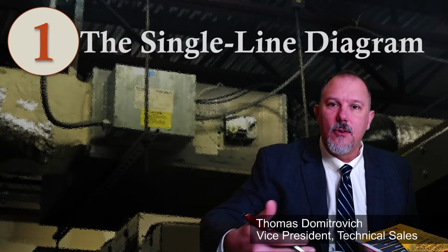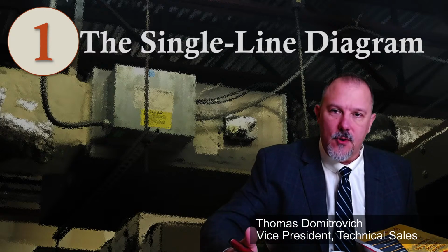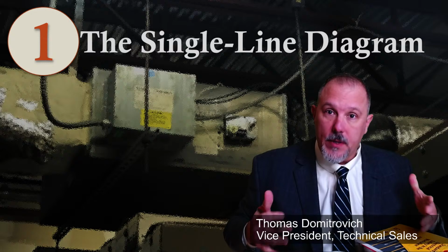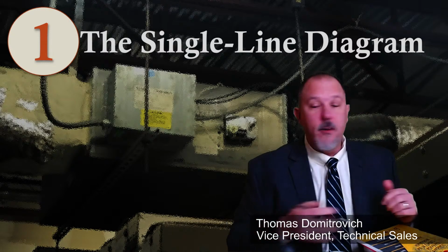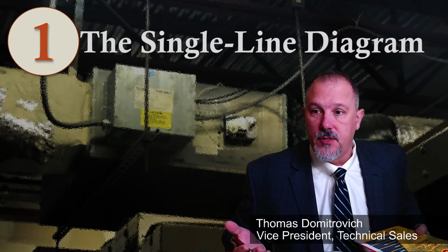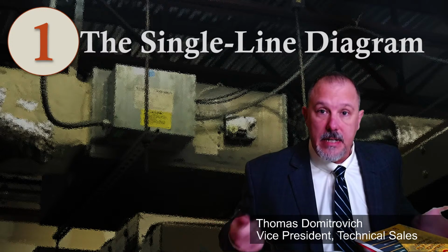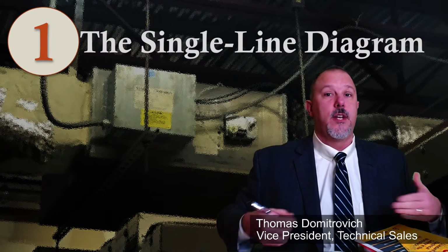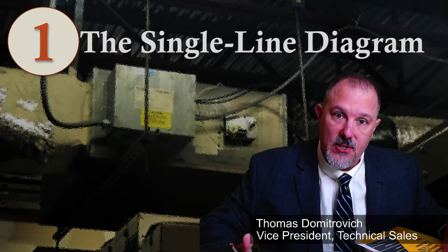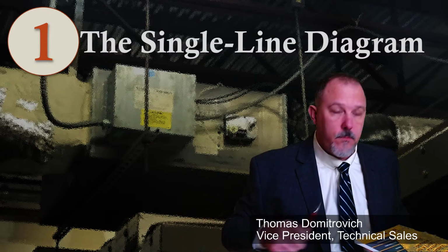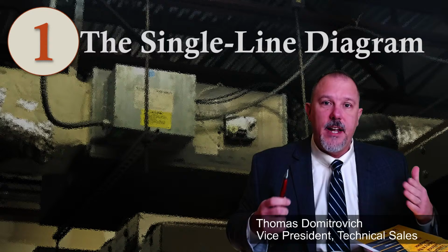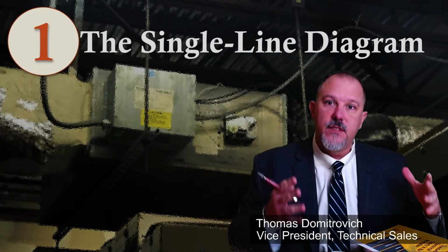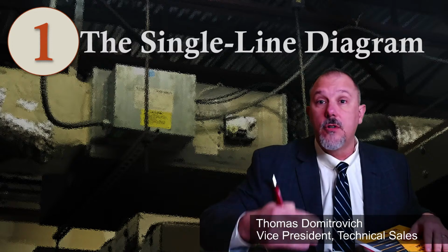We have this thing called as-built diagrams and as-built drawings, and the reason we have that is because changes occur during installation. Rerouting conductors in a power distribution system makes a difference in incident energy. Why? If I add lengths of conductor, I could reduce the available fault currents, and I have an increased incident energy. So understanding the layout of your power distribution system is very important for the electrical worker.